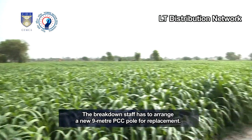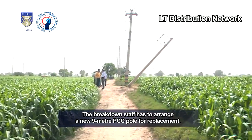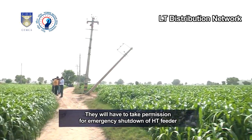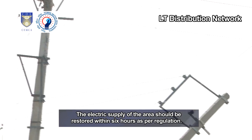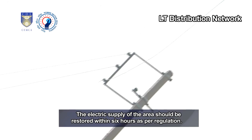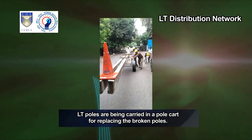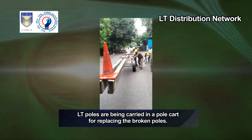The breakdown staff has to arrange a new 9-meter PCC pole for replacement. They will have to take permission for emergency shutdown of the HT feeder also, as LT lines are leaning over the HT pole, and for erection of the new LT pole. The electric supply of the area should be restored within 6 hours as per regulation. LT poles are being carried in a pole cart for replacing the broken poles.